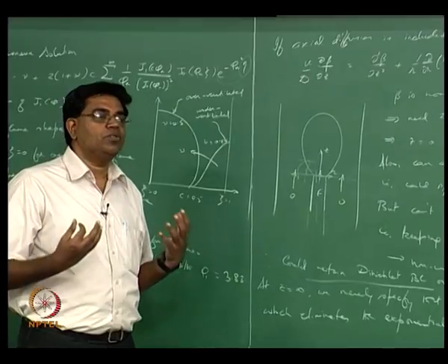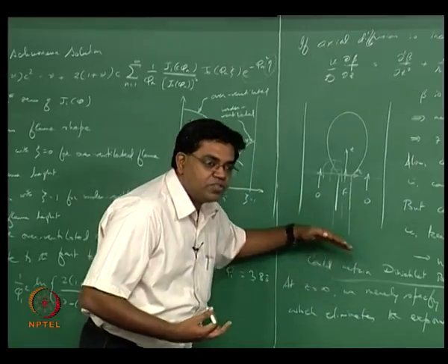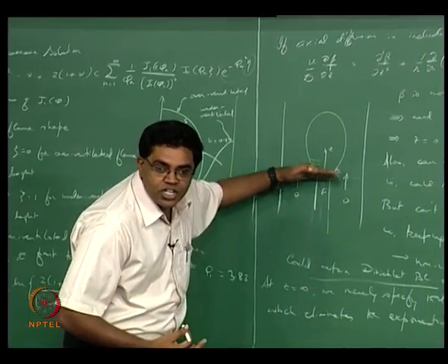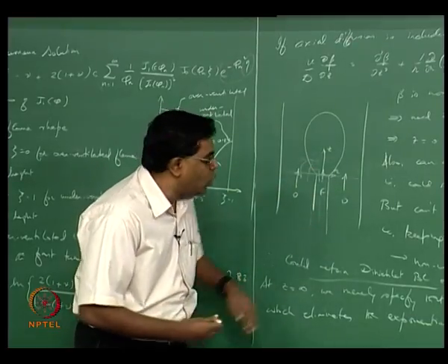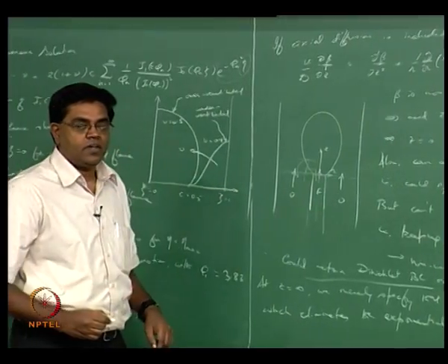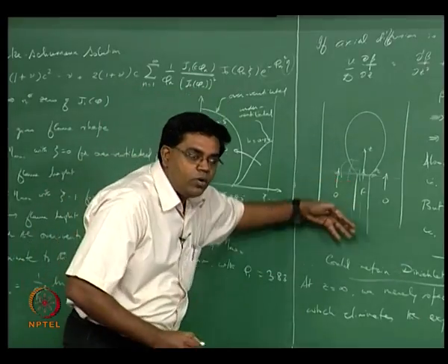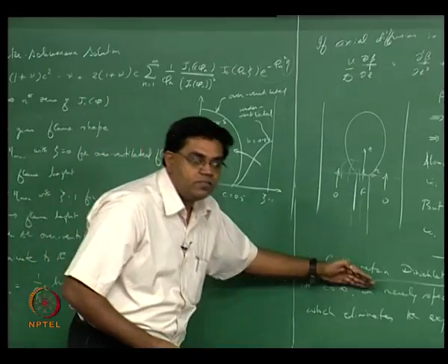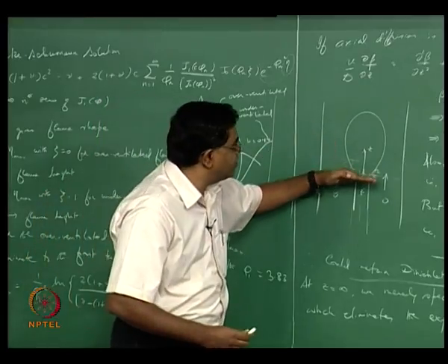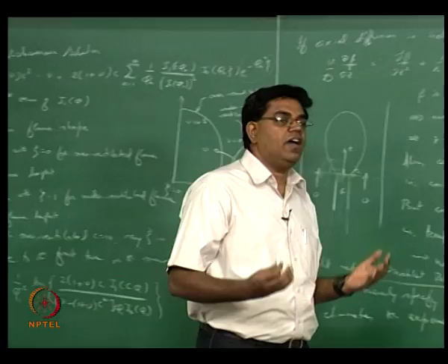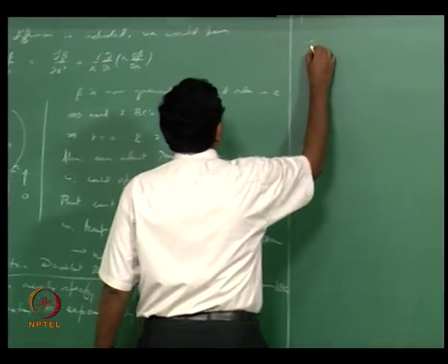So where can I expect to be sure that I don't have any contamination? Far upstream. Because you have a convection, there is a certain length scale associated with the diffusion in competition with the convection, right? And beyond that length scale you can hope to have pure fuel and pure oxidizer. But how do I know what that is unless I solve? And for me to solve I need to know the boundary conditions. So where do I go in search of the boundary? Do I want to now take like a minus infinity to plus infinity in Z for the domain? When in fact I am interested in what's happening here, that's where what is called a flux BC comes into picture, right? So we could now think about a flux boundary condition